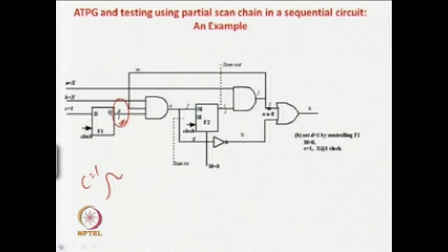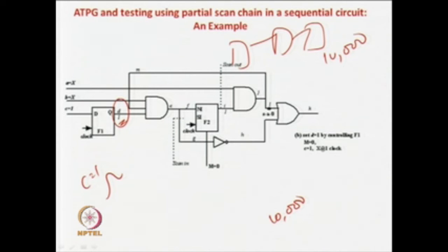So, what is the idea we have seen? Say we have used a direct scan chain based approach, so what would have been there? Say there would have been 10 flip flops over here, something like this. All are connected, say there are 10,000 flip flops in a chain. So, what you have to do? You require 10,000 clock pulses to set or reset them as required, correct? But let us assume that the sequential depth, that is DFF, is say 500 for these flip flops.